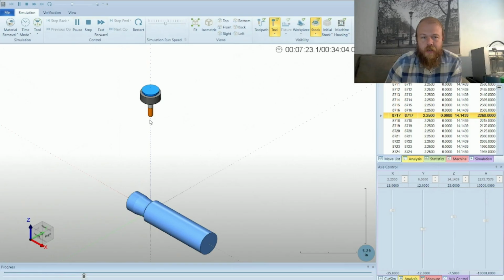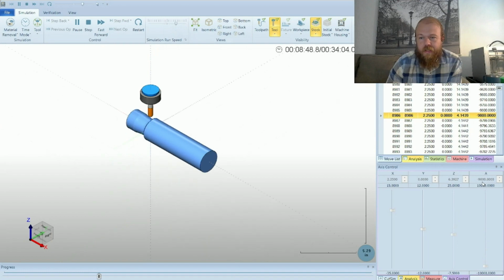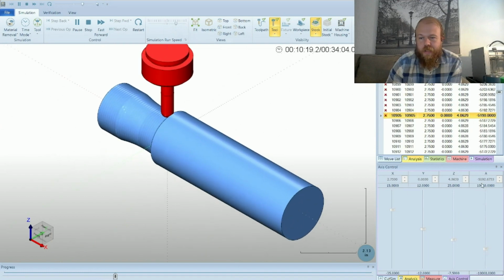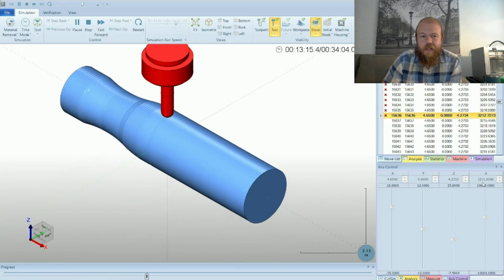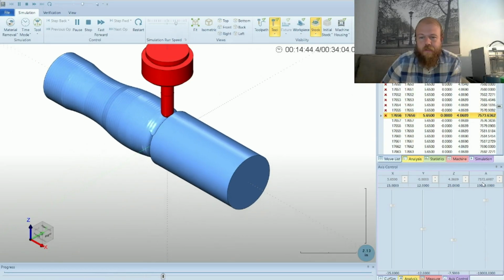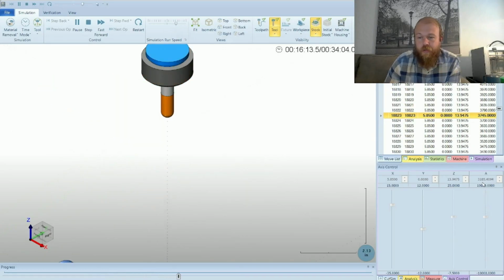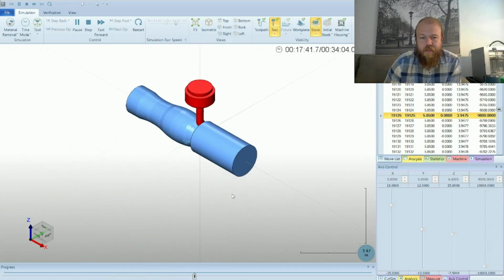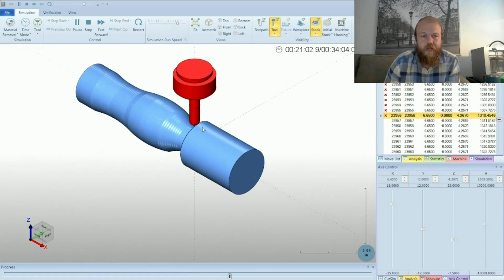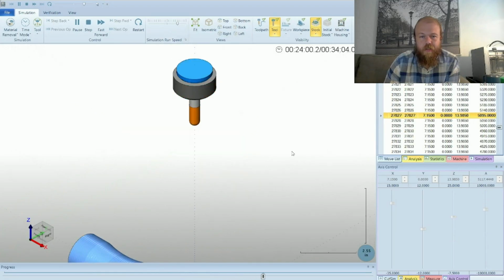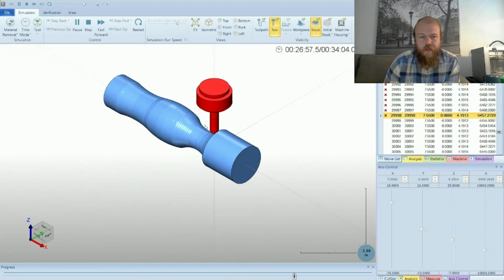The tool retracted up to a safe clearance plane, and now it's rewinding the rotary all the way to negative 9,999, and then it will start the operation again and start going in the positive A-axis again. So if you have a machine that has that type of setting, there's a certain limit in the X, Y, Z axes, or the A axis here. We can set the limit and make sure that it doesn't reach that limit. It'll do a retract and a rewind for your machine.